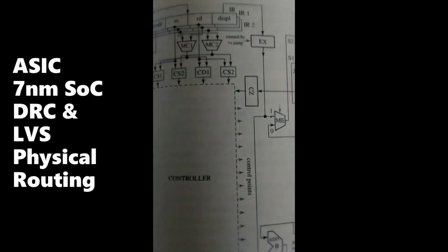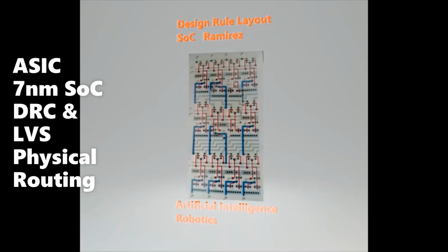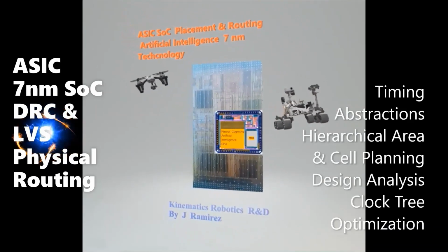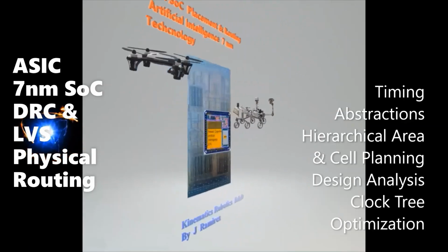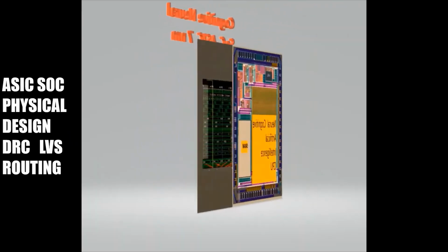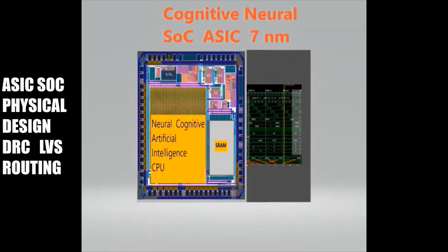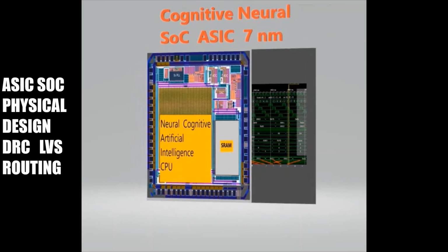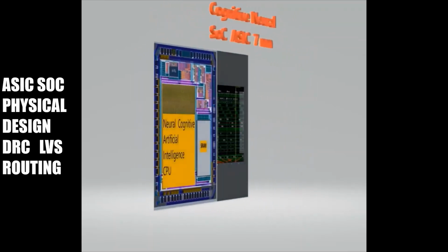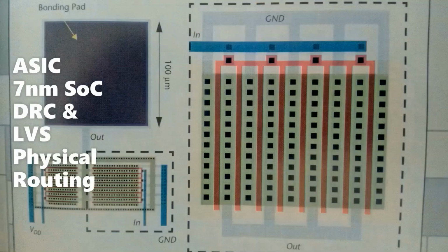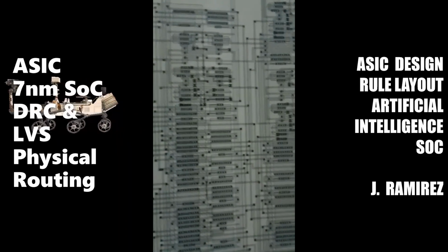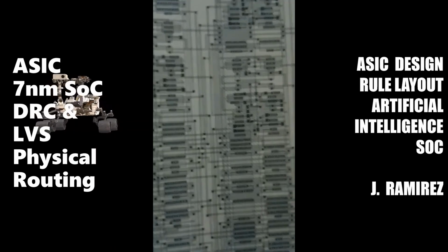The most important points in the routing segments are: routing is divided into global and detail routing. Routing algorithms should match the placement algorithms. Routing is not complete if there are unroutes. Clock and power nets are handled as special cases, and clock net widths and power bus widths must usually be set by hand. DRC and LVS checks are needed before a design is complete.